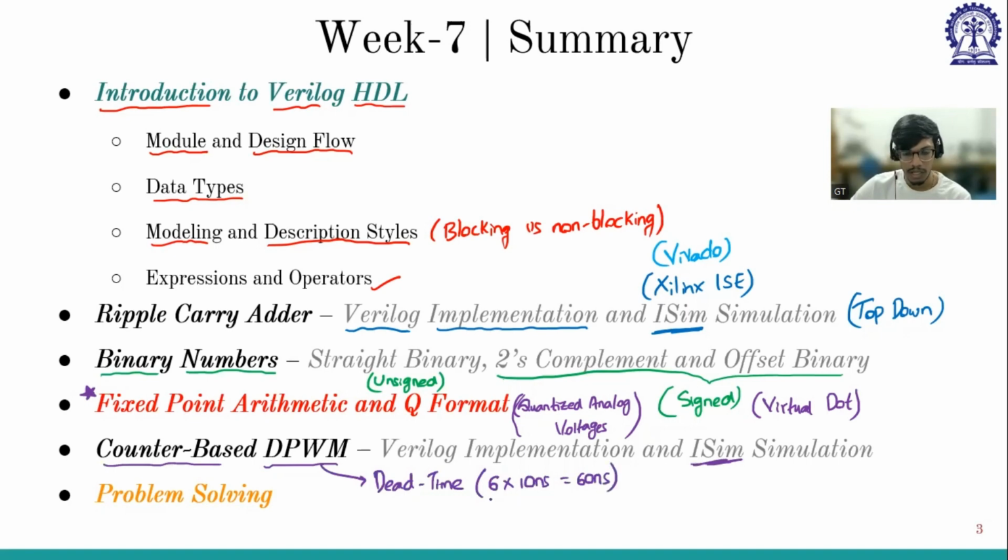Depending upon the application, you should design how much the dead time should be, and then accordingly insert the dead time, and check whether the dead time is working or not. Else, if there is any short circuit, like in the case of a buck converter, what I mean to say is the high side and low side switch should never be turned on at a time, else it will be short circuited and the switches will get damaged.